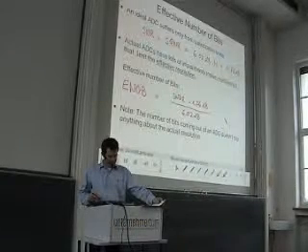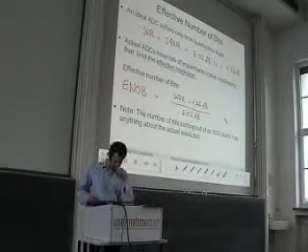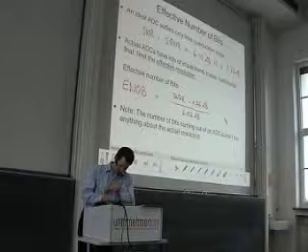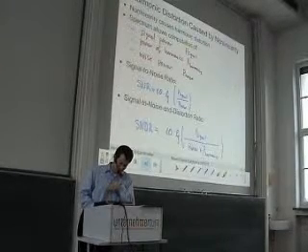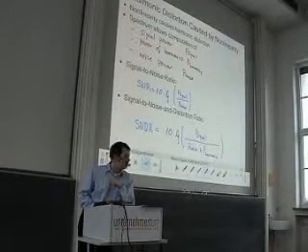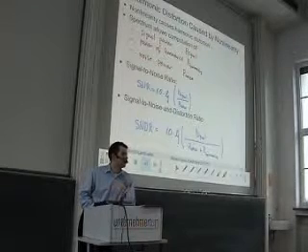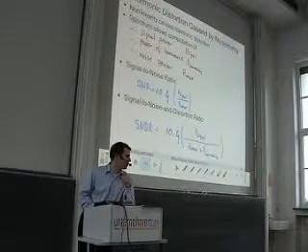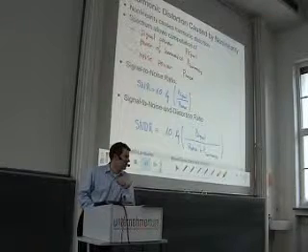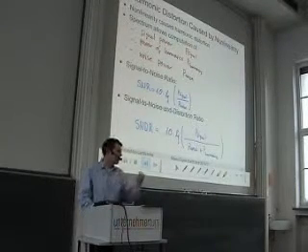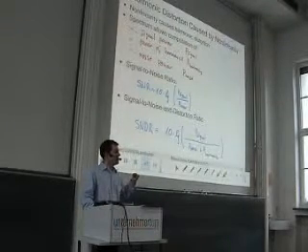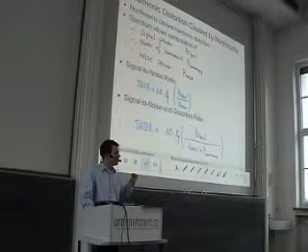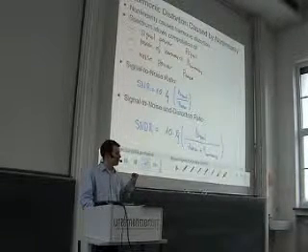Then, if you look at this definition, or in particular at this one, the signal to noise ratio is defined as the signal power over the noise power. So obviously, if we use a small sine at the input of our ADC for the test, then the signal power is small.